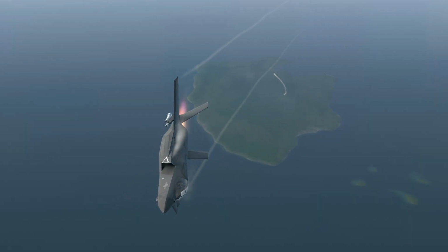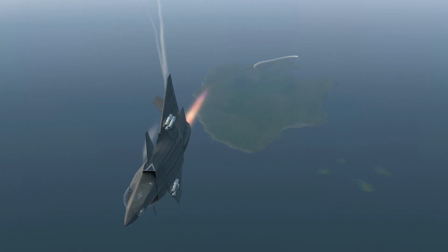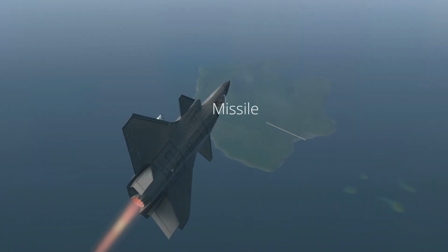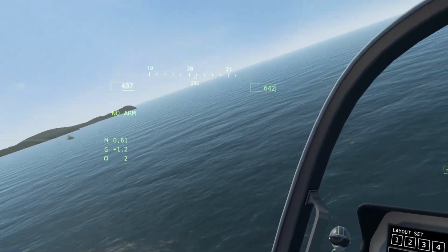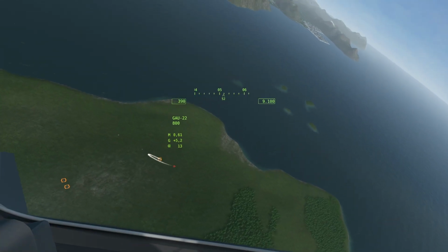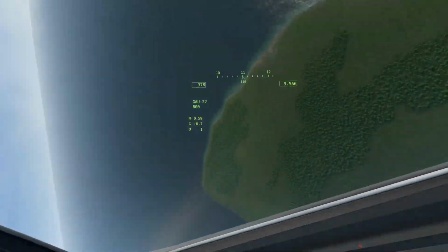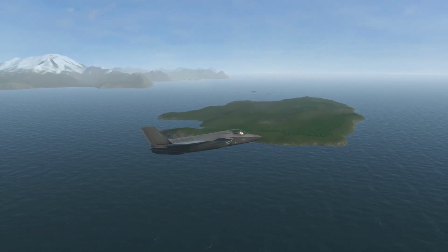If there is no cover and the missile is far away, by changing flight directions and gaining altitude, we can make the missile lose energy, or we can guide the missile to the ground or into a mountain. This is possible because the missile heads to where we're going to be and not where we are. If all this is not possible, we must use chaffs.